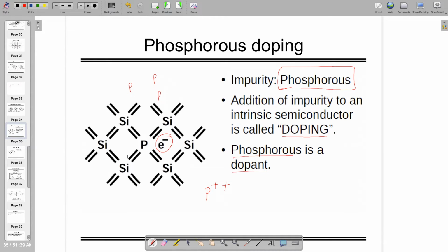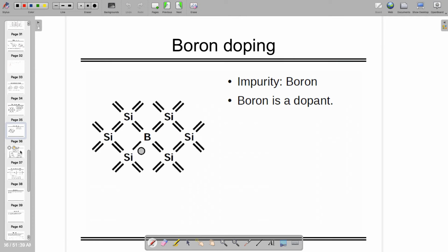So if you want an N type or P type semiconductor, you are going to make it with either column number 5 or column number 3 together with column number 4. Column number 4 has silicon. You can also use other things like carbon or germanium, right? But if you are adding boron, which is in column number 3, it will create one hole, right?